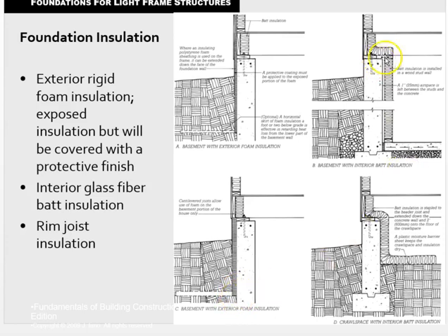And then just another variation on that is rather than put the rigid insulation on the outside is furring out this wall by putting small studs at this location and then having batt insulation on the inside. And then another important point here is definitely insulating the cavity. So what we see here is the joist running over, sitting on the pressure treated sill. There's the subfloor, and this would be the floor joist cavity, I would call it.